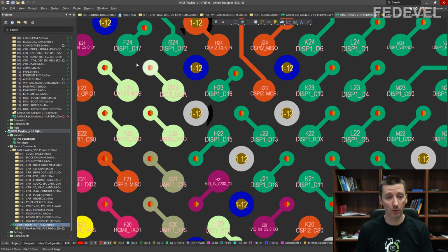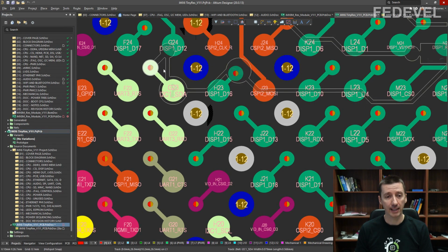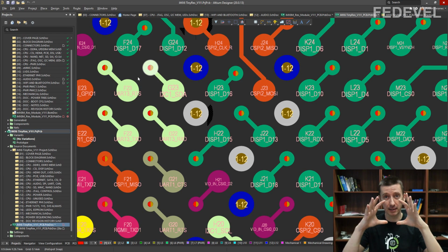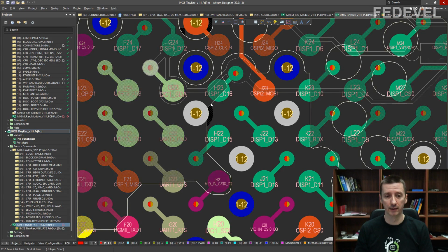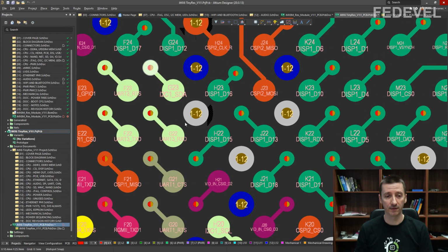You will need to go with microvia in pad, because these microvias can be much smaller than these through hole vias. And as I said, now I'm interested to know how small these vias in pad or microvias in pad can be, what we can use and what are the limits when a PCB is manufactured. And that's what we are going to speak about in the next clips.